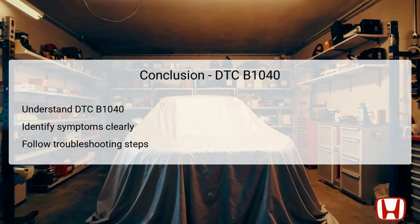involves understanding the implications of the body control module losing communication with the front wiper system. Recognizing the symptoms can lead to quicker diagnostics and repairs. Following the outlined troubleshooting steps meticulously will help to pinpoint issues in wiring, connectors, or components accurately.